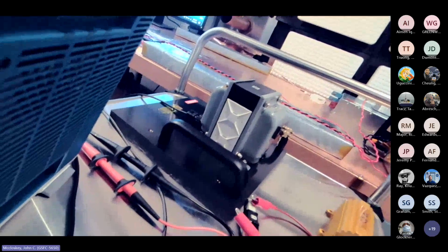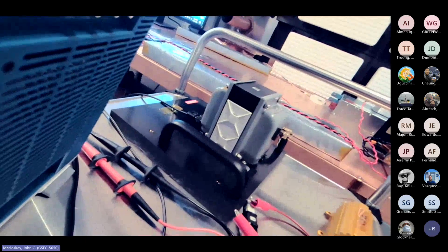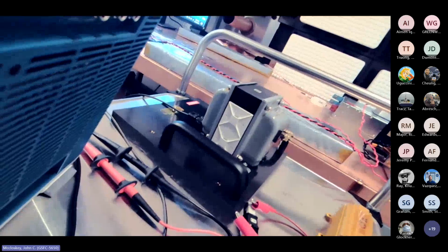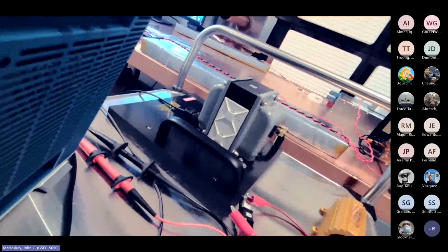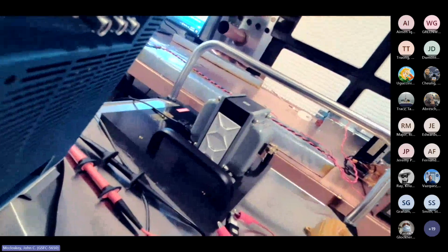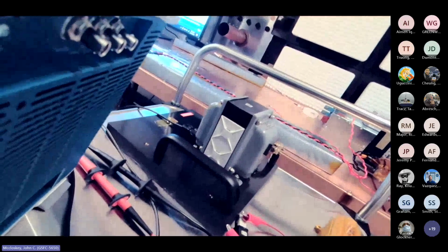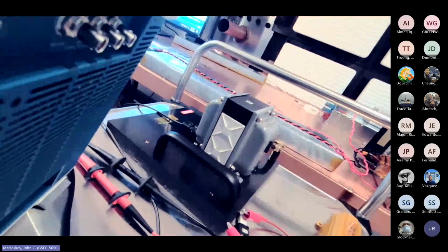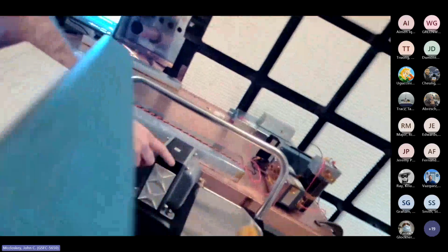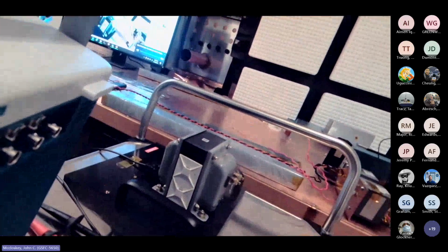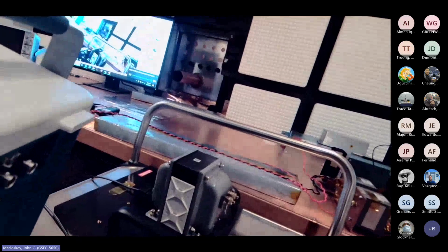Even CS114, the injection is a little bit less efficient, and when you're looking at radiated susceptibility RS103, you certainly can stress and damage hardware with radiated susceptibility, but the coupling is much less efficient, so that if you screw up and do an overtest with RS103, it takes a pretty significant screw up to get to radiated levels that could potentially harm flight hardware. Here, you're injecting your signal directly in line with the power feed to the unit. So if you screw that up, the threshold between the screw up and possibly damaging flight hardware is not very high.